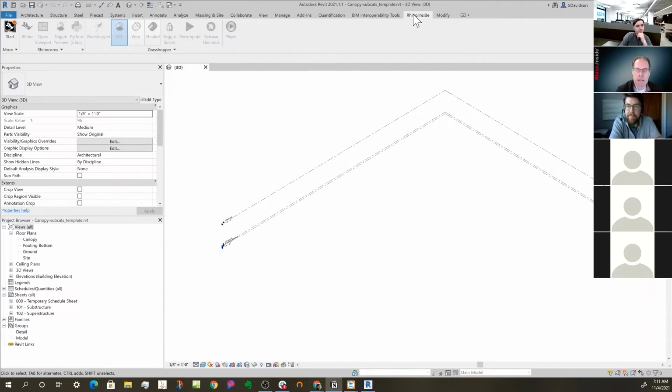What this takes, I think Rhino-Inside.Revit runs in 2018 through 2022 now. You install Rhino on the machine, you install Revit on the machine. You don't have to do it in this order. And then once those two are on the machine, then you install Rhino-Inside.Revit, which you can download for free. It's an open source project, and you install that. And what that does is that it installs this toolbar here. And so from this toolbar, we can do everything that we need.